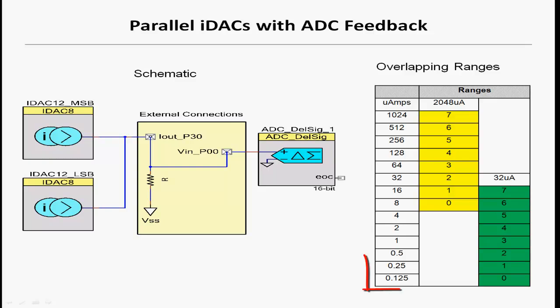Although we have 14 bits of resolution, the 2 extra bits are needed to achieve a proper trim for the 12 bits of linearity. This configuration can give the user 12 bits of linearity, but requires multiple 16-bit readings from the ADC each time the output is changed. This will limit the update rate to about 100 samples per second.